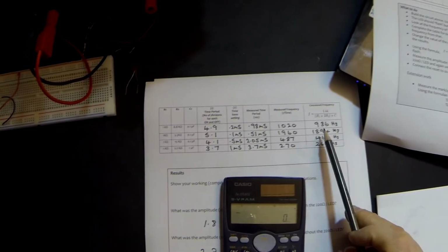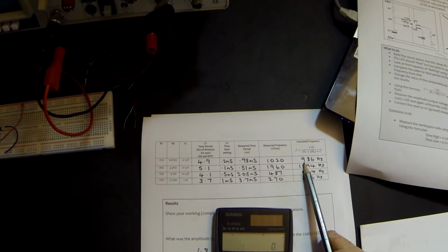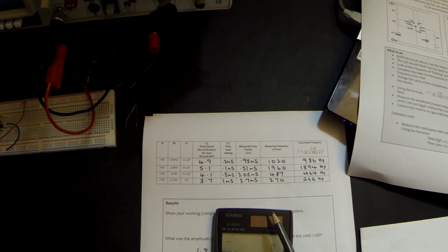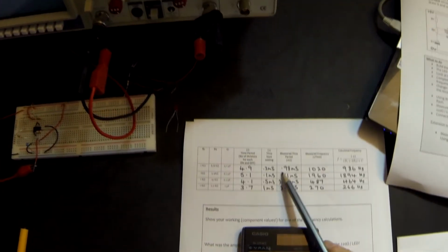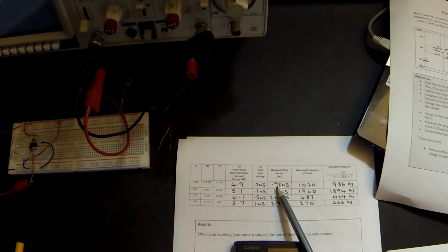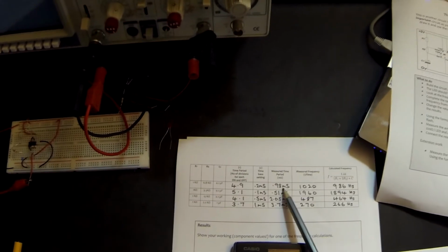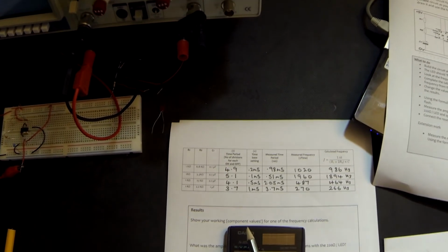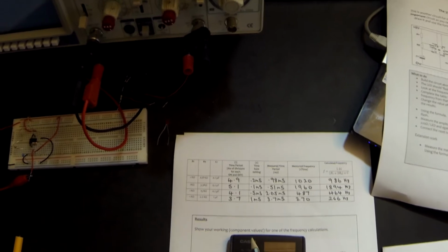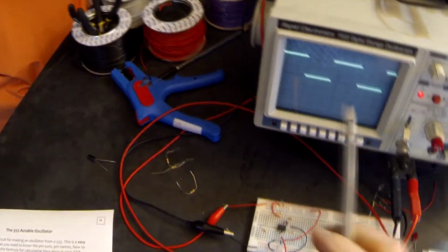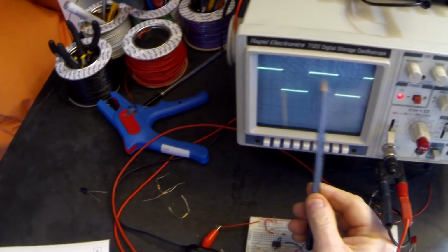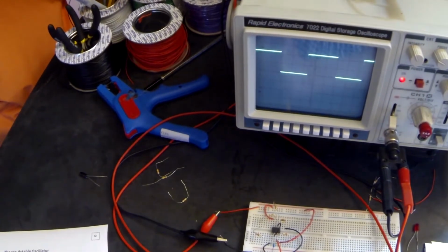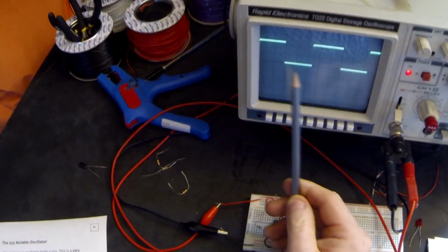So if we go back to our original values, when we look at it, we worked out that the frequency would be 986 Hertz. But we had measured on the oscilloscope that the mark plus the space was 0.98 milliseconds. And therefore our frequency was 1020 Hertz. Sometimes it may be useful that you don't want an equal mark space ratio. And we can quite clearly see from our oscilloscope trace here that our space, mark, space distances are pretty even. I'm not going to measure them accurately right here and now, but we can see that they are fairly accurate to one another.